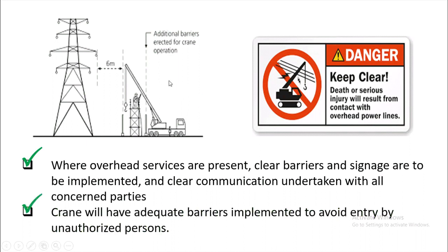Cranes will have adequate barriers implemented to avoid entry by unauthorized persons. So again, barriers are to be provided on the perimeter of the lifting area of the cranes. This is to prevent any persons from entering that location or the danger zones when you are performing the lift.